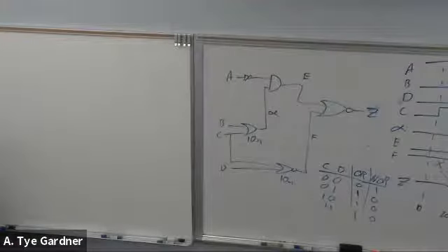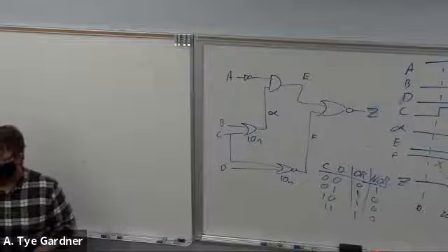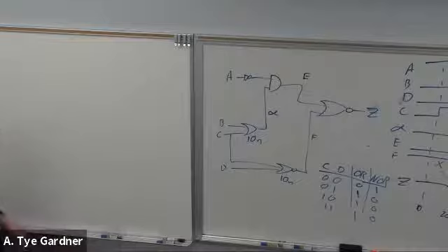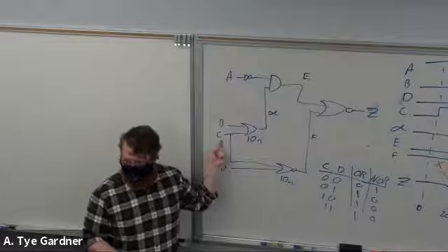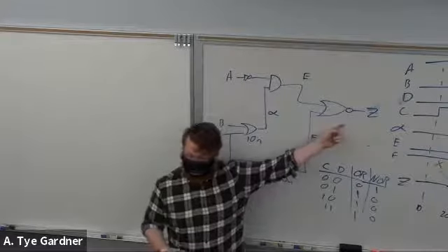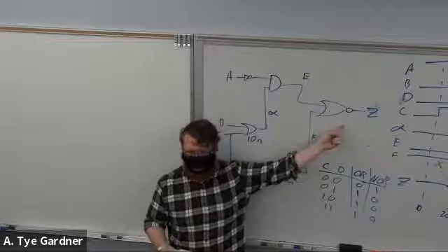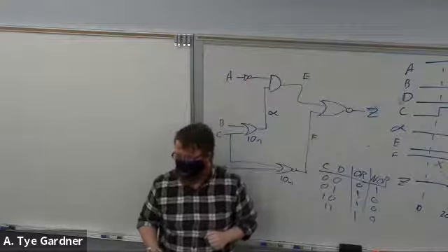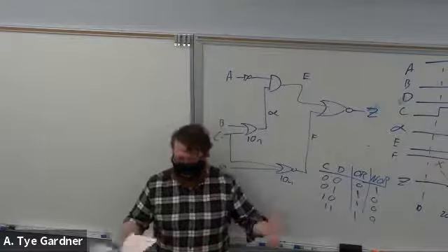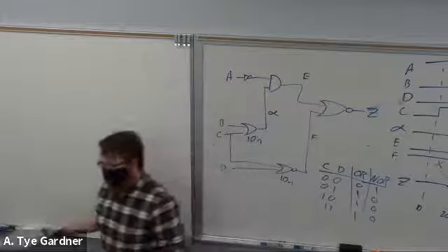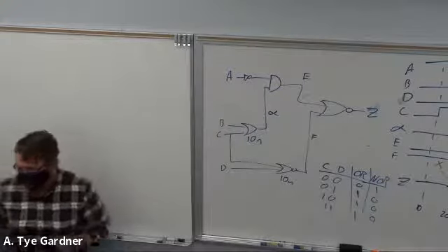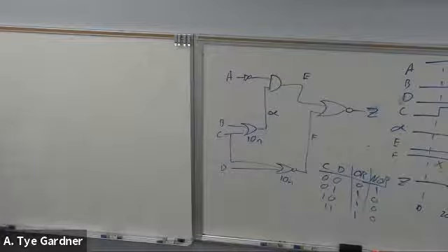So if you prime it correctly, then Z should stay the same the whole time. Yeah. And when it changes, that's how you prime it. And I could even ask more simply, because if C is the only one with a differing delay path and the output changes when C changes, it's not the same, so there's no risk for static hazard there. That's where dynamic hazards come into play, but we're not talking about those. I've left that for next semester, whenever you take 3610.